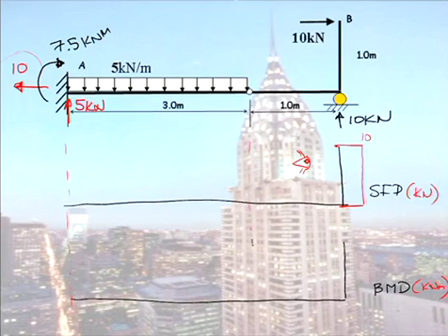Shear force diagram, bending moment diagram. Shear force shouldn't be too much of a problem. We start at the left-hand end and we follow the loads. Where there is no load occurring, you move constantly across. If you have a uniformly distributed load, it reduces uniformly, linearly.